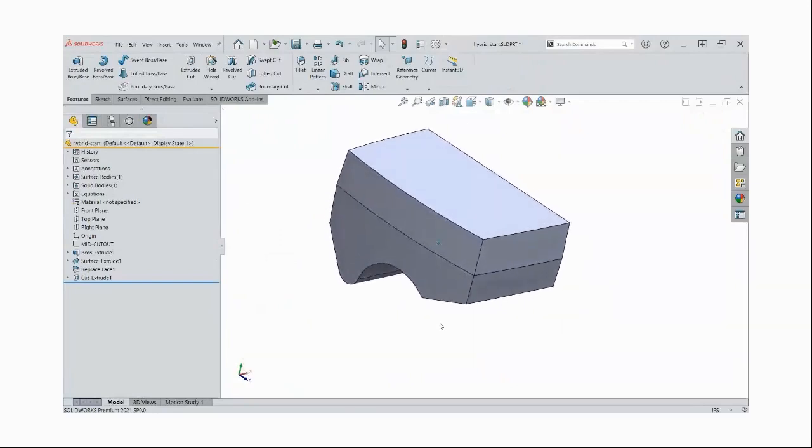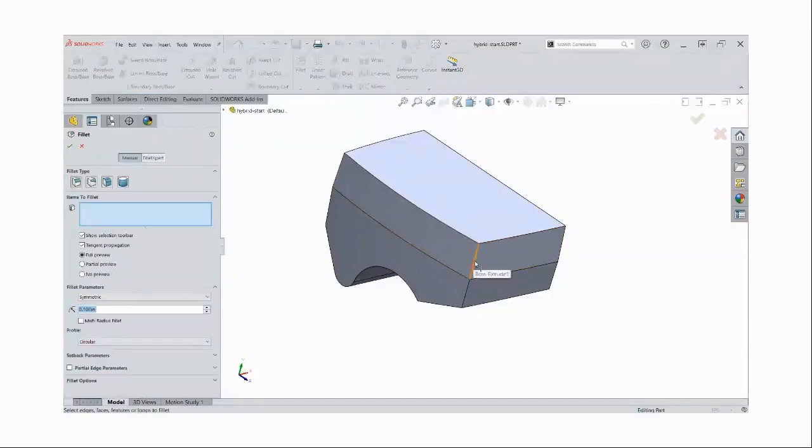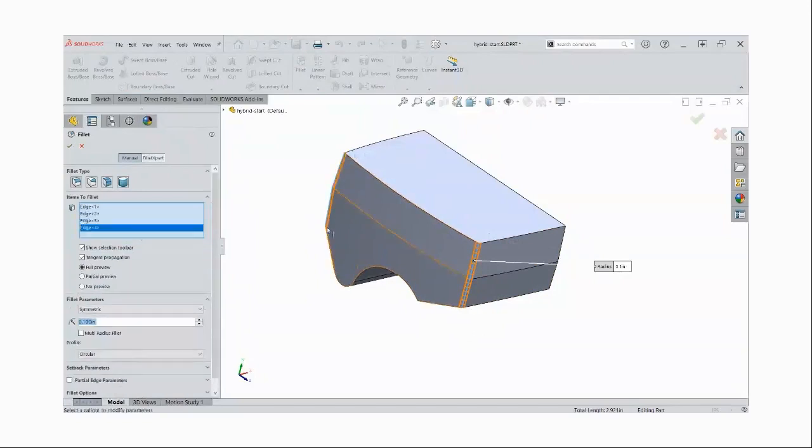So the fillets are what's going to make it look a lot more pleasing. Normally, I would say apply your fillets closer to the end of the modeling tree, but in this case, these are going to be really big fillets I'll be using, and I want them on sooner. So I'll go into my fillet shortcut and start clicking these edges. So one of the benefits of modeling the top and bottom at the same time is I can apply the fillets to both of them. I can do operations to both halves. Again, we're eventually going to split these halves apart. I can apply operations to both halves at once. So that's a 3/4 inch fillet.